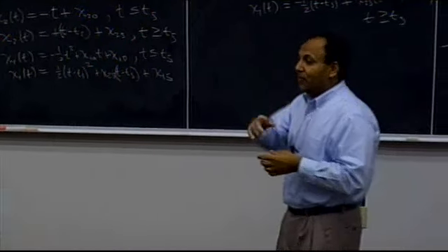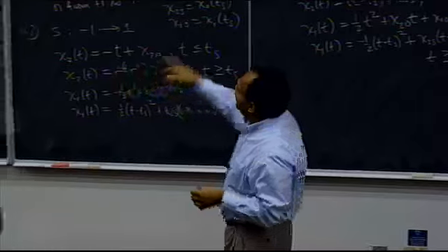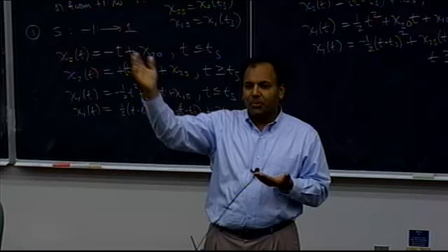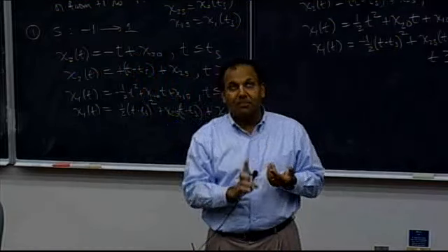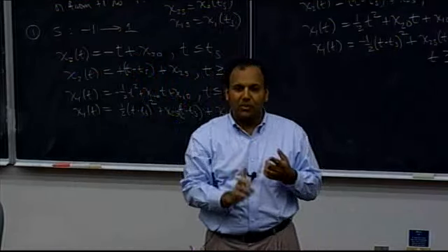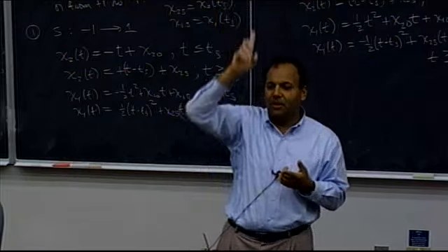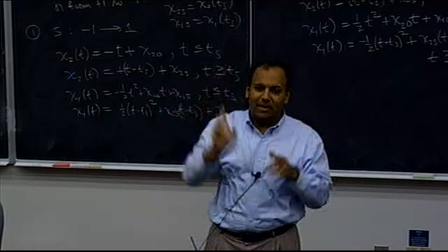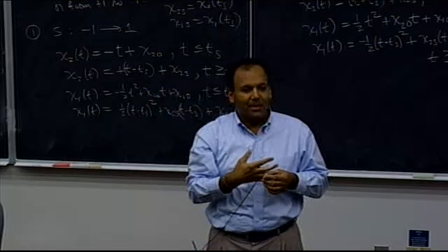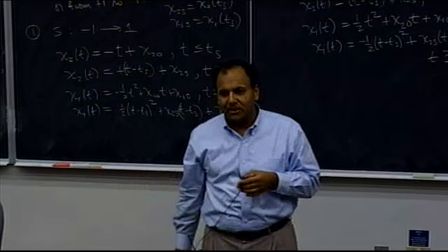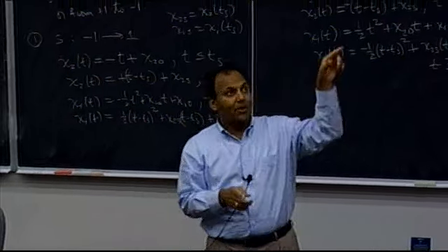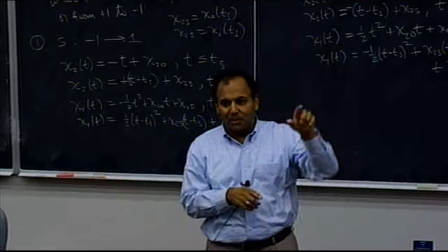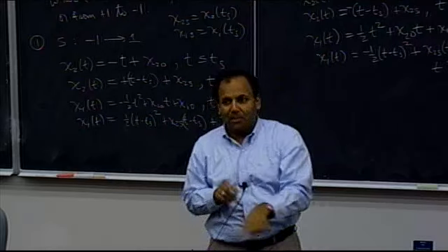One of the famous problems like this, where you would think that you would actually go through this kind of an analysis, is what's called the Goddard rocket problem. The Goddard rocket problem is a maximum ascent of a sounding rocket. So it's just a one-dimensional rocket. You're literally firing it vertically, and you want to maximize the final altitude. That's the goal. Free time, you want to maximize the final altitude, right? That problem, the solution actually lies on a singular arc. There's an arc on the trajectory where the control is max, and then it goes along the singular arc, and then it's min.